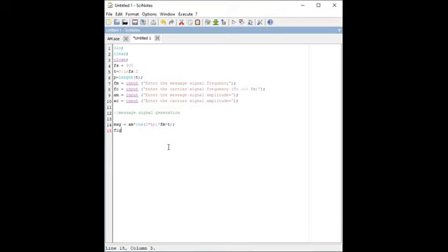Now I want to plot this signal, so I am going to consider figure 1, and I will divide that figure 1 with subplot into 3 categories. In the first window, subplot 3 comma 1 comma 1, I will plot time versus the message.